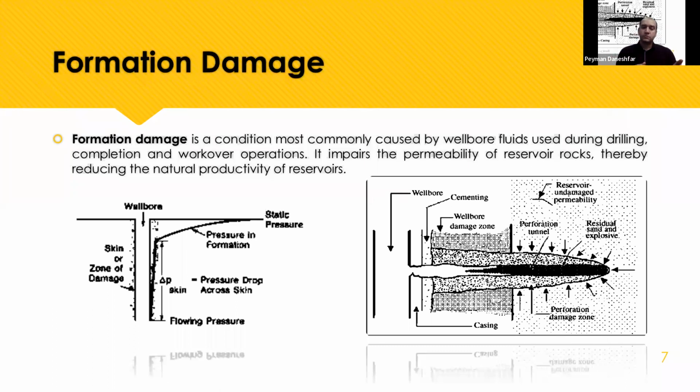When you see that your radius of damage zone increases and your permeability decreases, you need to use one of the stimulation techniques, such as acidizing.